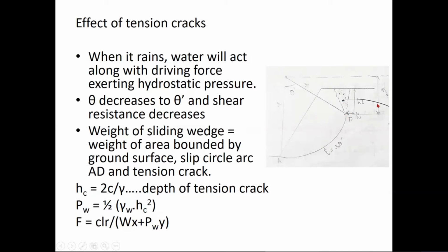And that distance is y. As you can see here, Pw acts at a distance of y from the surface. So the total moment will be Pw into y. So my factor of safety here will be equal to CLR by Wx plus Pw into y. So this is the effect of tension crack and effect of hydrodynamic pressure or hydrostatic pressure if that tension crack is filled with water. Is that clear?